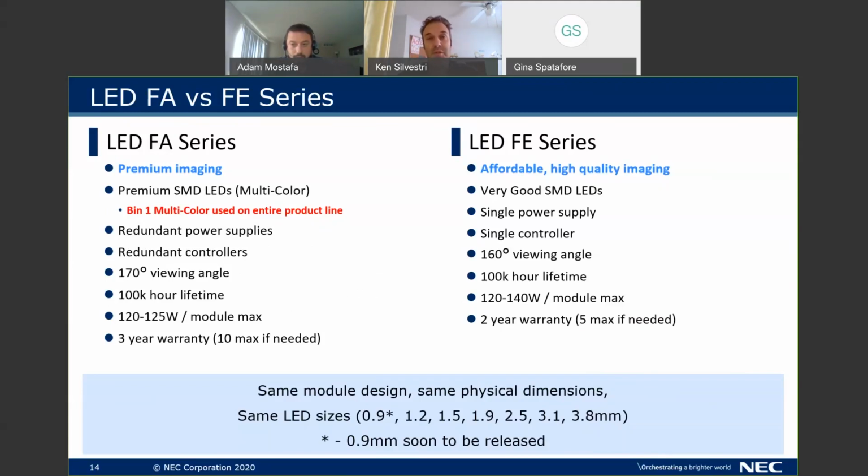100,000 hours, if you're using the wall 24 hours a day, 7 days a week, that's 11.4 years. It is based on general usage, not 100% brightness, about 30 to 40% brightness, and using full motion video on it. Don't focus on this number when you're looking at LED solutions. If this is going to a corporate boardroom that's being used 8 hours a day, a 70,000 hour LED will last you over 30 years at that usage.